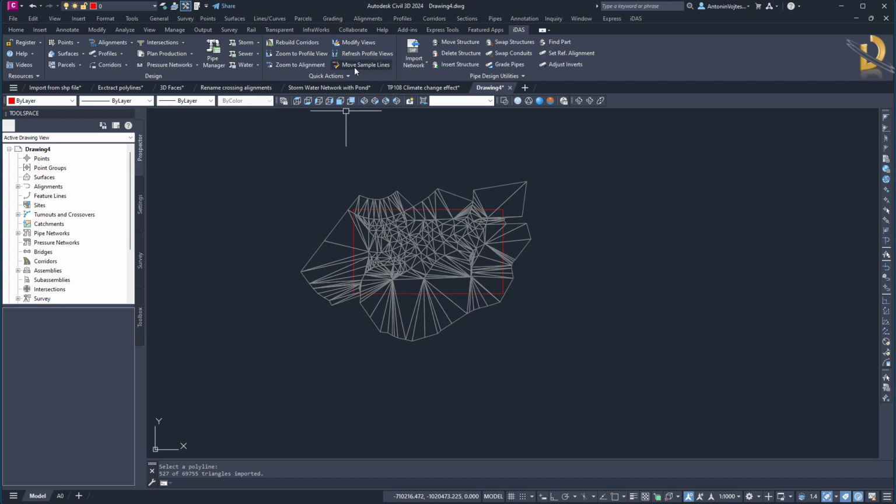Now, another tool we developed is to delete empty sites. We sometimes get drawings from clients that contain a lot of empty sites. If that's the case, you can delete them with default Civil 3D functions, but sometimes it hangs forever and nothing happens. So that's why we developed this command, just to make it easier for the users. If you get a lot of empty sites for whatever reason, this is the command to use to clean them up. We also plan to provide a little more functionality where you can select the sites you want. You can even probably select the sites with the object. We don't know yet, but this is just the first attempt to make the user's life easier.